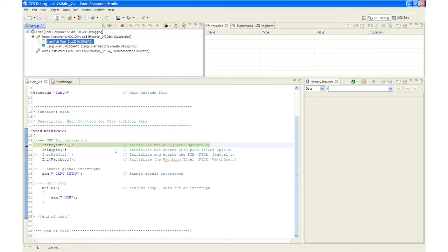What has happened is as follows. While the code was running, the watchdog timed out and reset the processor. The reset vector was then fetched, and the ROM bootloader began execution. And since the device was in emulation mode, as you might remember, the emulator is connected, the bootloader read the EMU_KEY and EMU_BMODE values from the PIE RAM. Okay, these values were previously set for boot to M0 SARAM boot mode by Code Composer Studio.